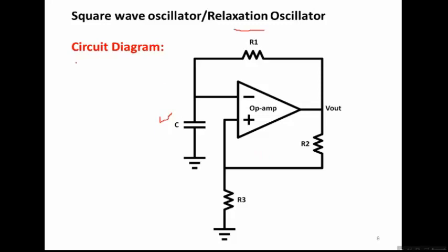You may have come across sinusoidal oscillators in which an inductor and a capacitor can be used to produce a sine wave, but a simple LC circuit cannot produce continuous sinusoidal output or sustained oscillations, because as time goes, the energy stored in the capacitor or inductor keeps dissipating, and as the energy decreases, the oscillation starts dying out. So you have to refresh that energy after a certain interval of time so that oscillations can be maintained.